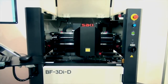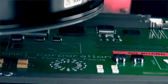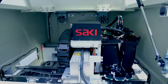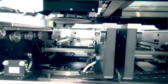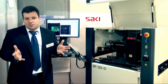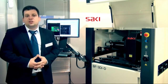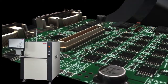The brand new gantry can accommodate three versions, starting from dual lane, single lane for L size, and the XXL size version. The gantry is driven by a ball screw, whereas the previous generation was driven by linear motors. And the programmable projectors were optimized in a way that we changed the projection angle in order to eliminate the secondary reflections, and the homogeneity was improved. Therefore, the height reconstruction is much more reliable compared to the current generation.